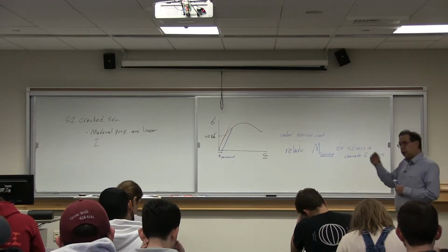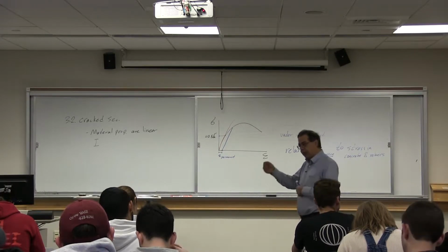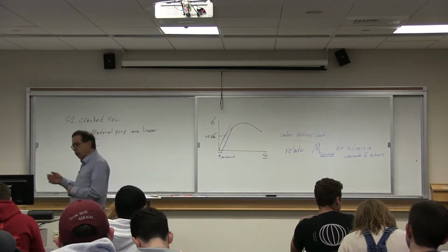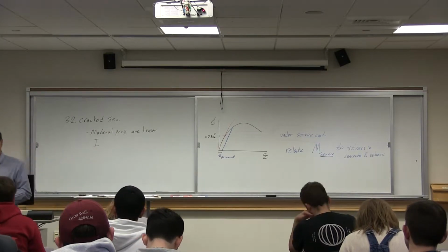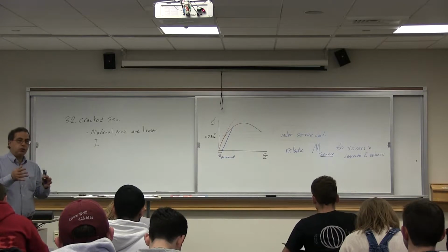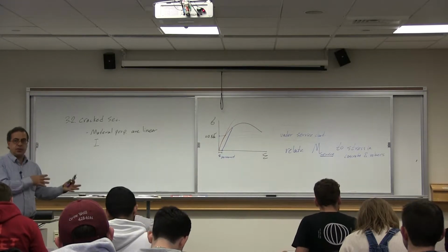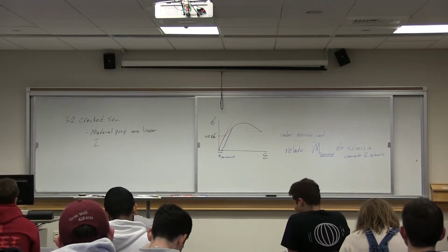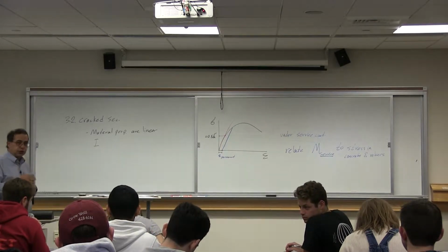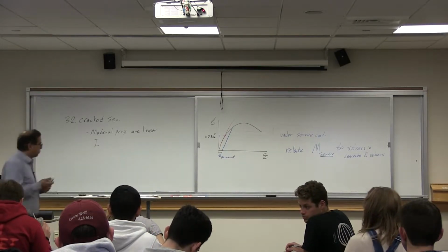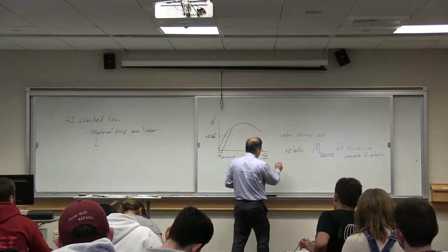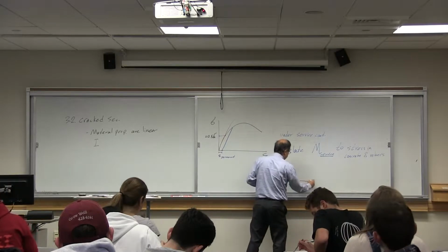What we said is we don't want concrete in compression to have compressive stress more than about 1/2 of f'c. The second question is, what should we do for rebars in tension? Don't want your rebar to surpass 60 ksi in stress, which is the yield stress. So that would be one starting point. We will modify it, but that's a good starting point to think about.